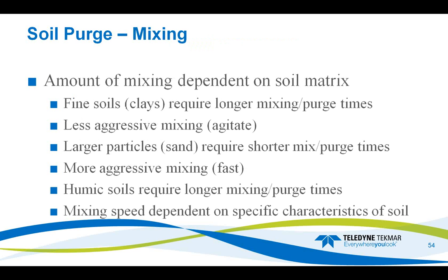Okay, for mixing, the type of mixing and the amount of mixing that we would use during purge is going to depend on our soil matrix. So for fine soils such as clays, we need to mix longer, so maybe we need to do a pre-mix before starting purge. And then maybe we need to increase our purge time to make sure that we get adequate contact time between that very, very fine particulate clay and the water so that we can remove more of those volatiles from the clays to the water and then purge them out.